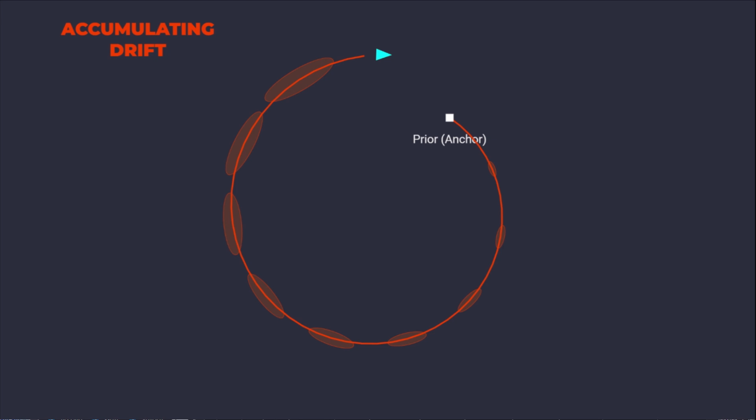A fixed initial pose constraint, often called a prior, anchors the entire graph, preventing translational and rotational drift of the entire structure. Without this anchor, the optimization problem is ill-posed, exhibiting a null space corresponding to rigid body transformations.